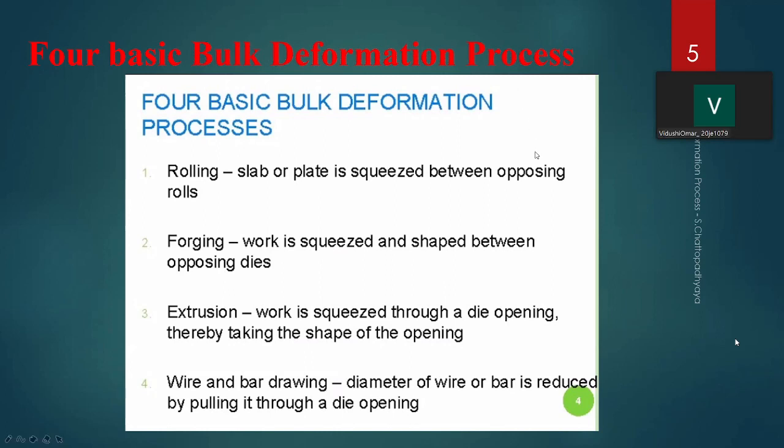If you apply a lot of force in the first go, super. I'm impressed about that. And I'm the best person to tell you here. The reason is I worked in a wire drawing industry. In one go, if you give that, there will be a possibility of crack.